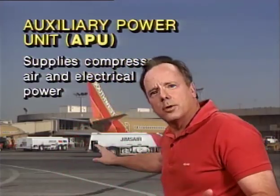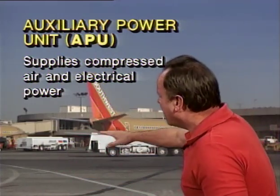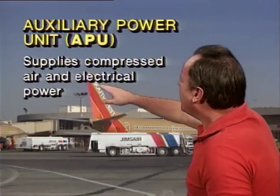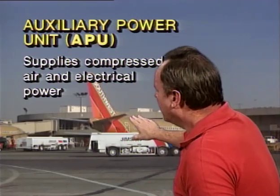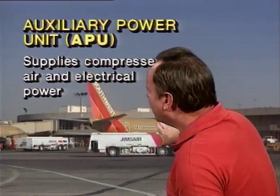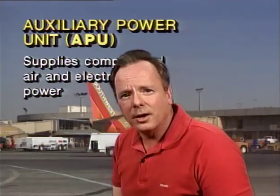And an APU is a little turboshaft engine that you can keep running. It's normally in between the main wheels or back in the tail cone of the aircraft. And that APU can supply compressed air and electrical power for the aircraft. And it's a very neat way of providing those services, much more efficient than keeping a main engine running. Let's take a look at an APU.